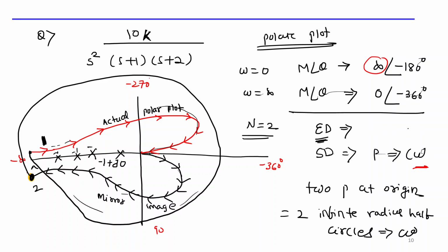So what you do is minus 180 and subtract minus 360. See the sign of this. What is the sign of this? Positive or negative? Positive. If it is positive, it is clockwise. If it is negative, it is anti-clockwise. That's it. For the starting direction, always see if poles are there or zeros are there.